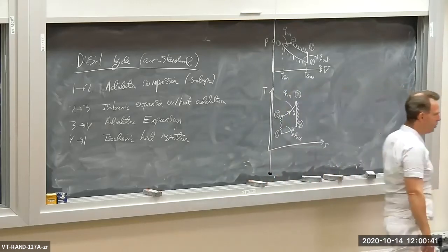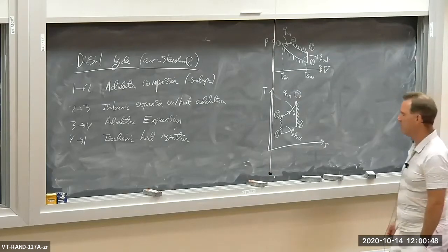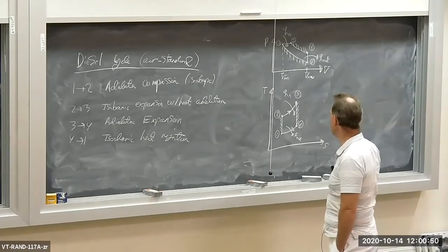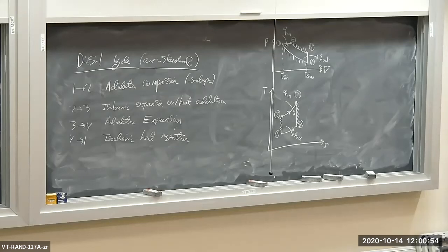Okay? So the work-producing cycle here takes heat isobarically, converts some of it into work, boundary work in this case, and rejects the heat isochorically. The PV diagram is quite informative because that tells you the various processes. The TS diagram tells you where the heat addition is occurring. Okay, that's pretty nice too.